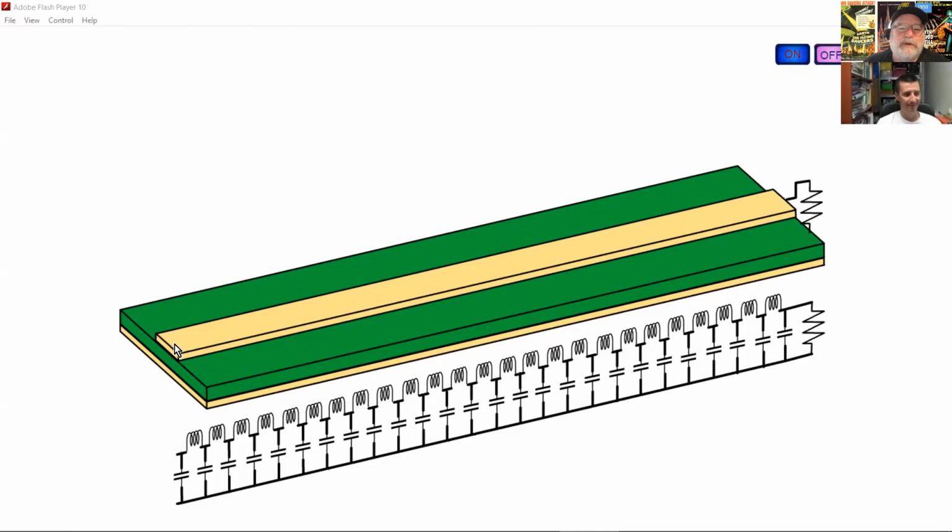And we think, okay, 20 milliamps goes down the line, it hits the end, and then it returns into the return path, and then it comes out and comes out. That's how we learn it in elementary school. It goes down one conductor and then returns in the other conductor. That's kind of what it looks like at DC, but that's not how it gets there.